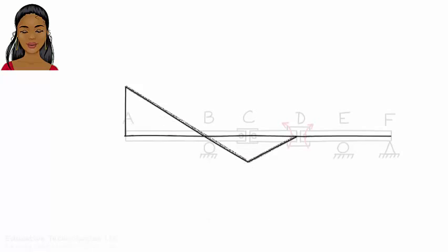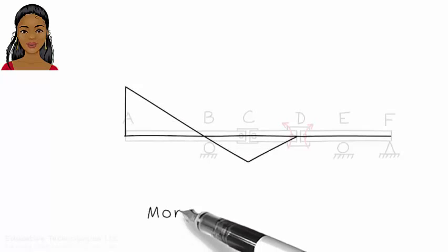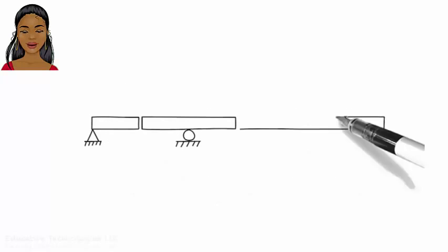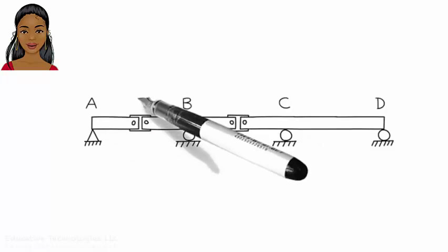It is important to note that for moment influence lines we cannot readily determine diagram values qualitatively. Further analysis is required when the diagram values are needed. For that reason, we generally draw the qualitative moment influence line only for determining vehicle locations that lead to the maximum moment value. We then have to analyze the beam to actually calculate the value. Here is an example illustrating this process.